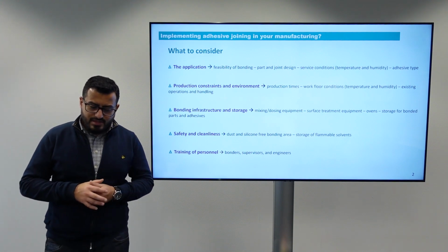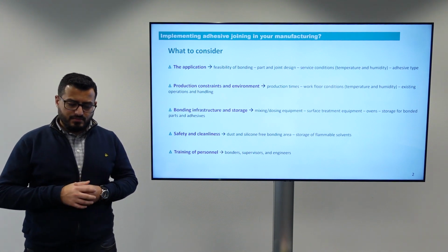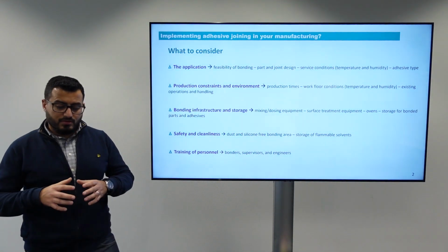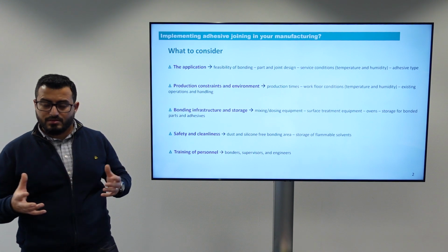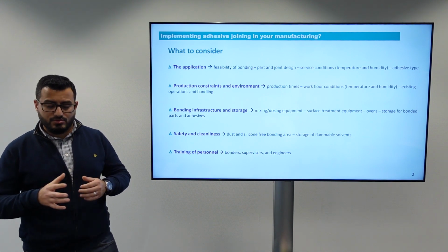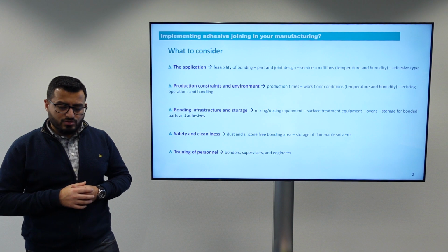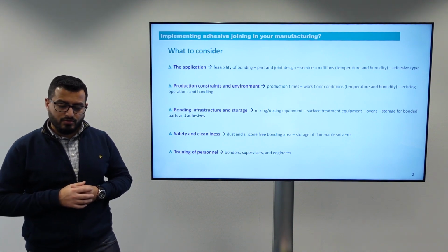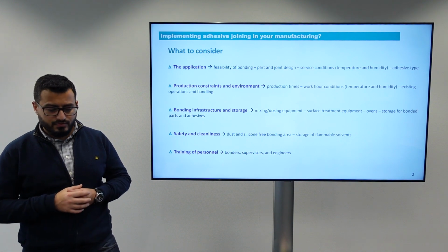The fourth aspect is safety and cleanness. So, of course, you need kind of a dust-free bonding area, also free of silicones. And you also need to have proper storage for flammable solvents.